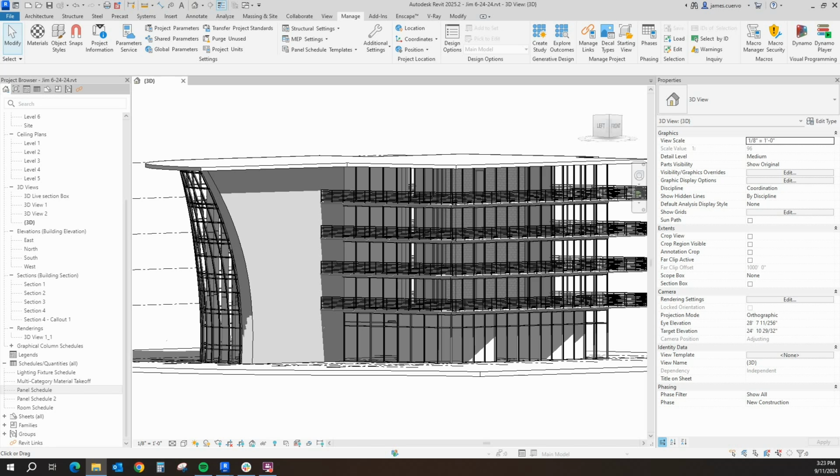Today's topic is the selection of multiple panels for the purpose of changing the style type. We have noticed that this selection can be a bit tedious and time-consuming, considering that there are often panels that have the same type as needed. Further, there is also the need to unpin them before we are able to modify them. In light of the above-mentioned facts, we've decided to create and show a possible workflow to do just this task without resorting to a Dynamo script. With all of that said, let's get going.